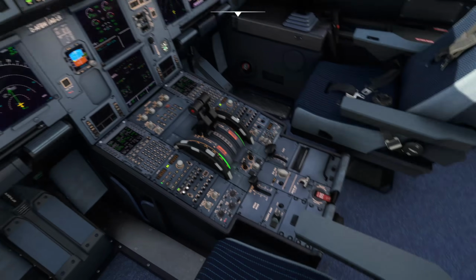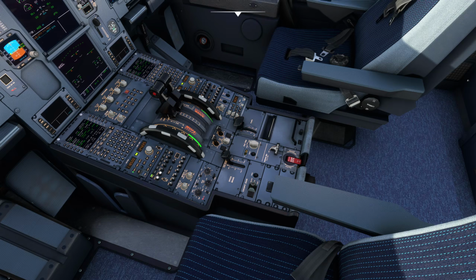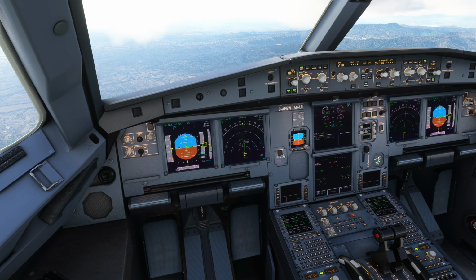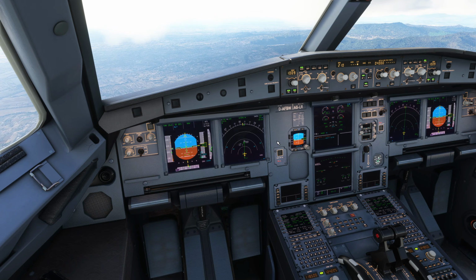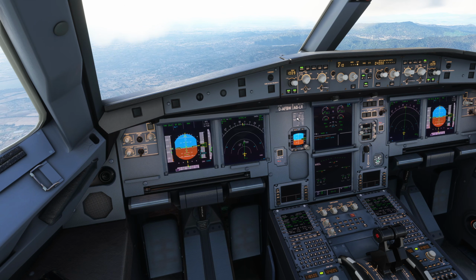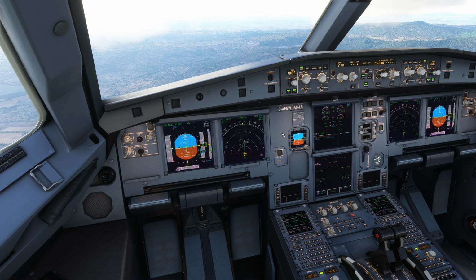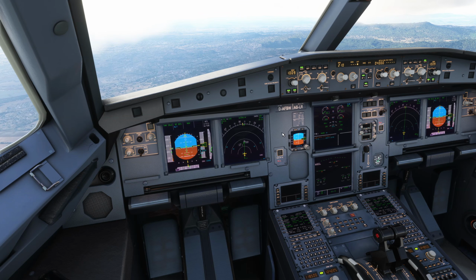So what is this handle actually going to do? When the time comes, we lift it up and turn it 3 times. When we do turn it, you're going to isolate the hydraulic system. Then you're going to unlock the gear doors, which are going to then drop down. And then with the last turn, you're going to release the locks and allow gravity just to drop the gear down into the extended position. You don't need to do anything clever after that. Airflow and weight will naturally do it. Remember, the nose gear, although it's lighter, will fall into position because the airflow will help it, and the main gear is very heavy and will drop out and lock itself into position as well. Very clever stuff, very simple.